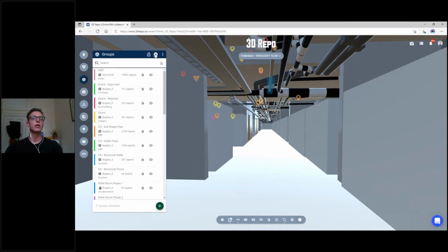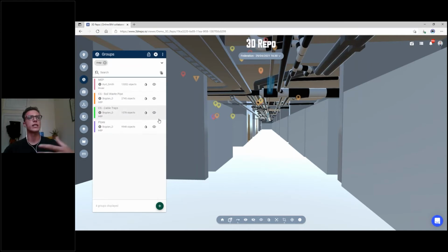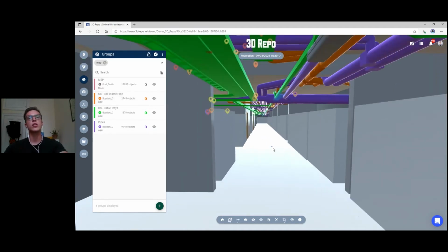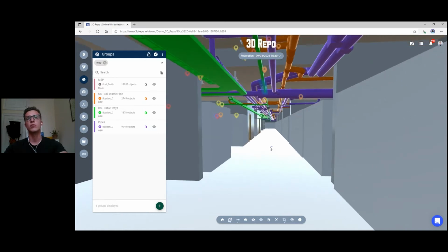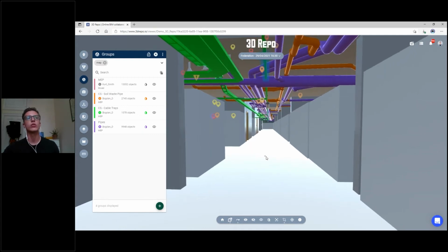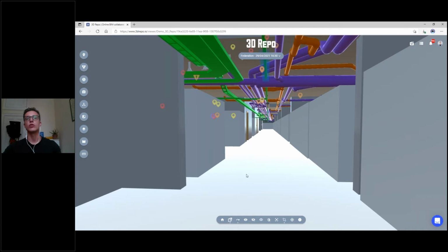I can then come into my space and then have a look where the MEP equipment is. So I can run my rule checks to tell me where the pipes are, where the cable trays are, where the soil waste pipes are. So this is where you suddenly start realizing that actually things don't have to be complicated, right? And to initiate that coordination process, it takes just a few clicks of a button like here. I can easily jump to an area of interest. I can easily visualize what certain discipline carries, what data it has, and so on and so forth.